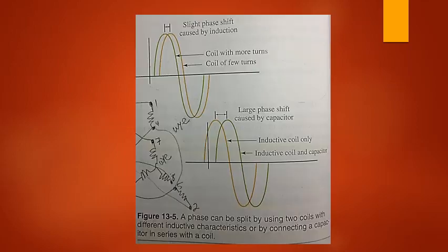Single-phase induction motor. Single-phase induction motors are used in many home appliances where three-phase electricity is not readily available. Most single-phase motors can be run in either clockwise or counterclockwise direction. To reverse the direction of rotor rotation, you must reverse the connections to the start windings. Not all single-phase motors are designed for reversing rotation.